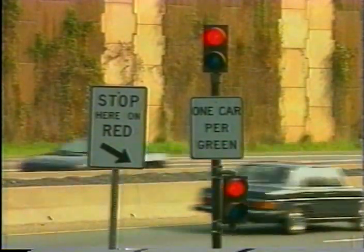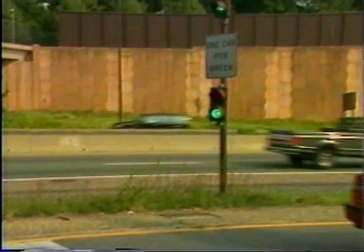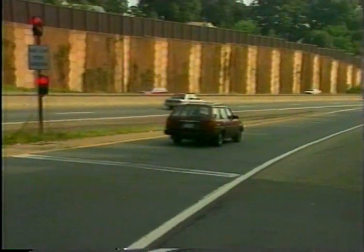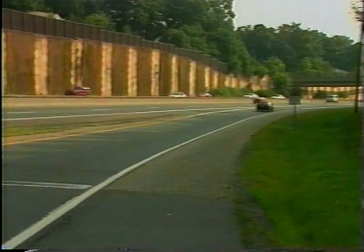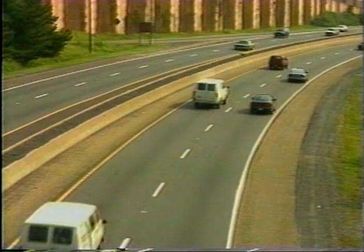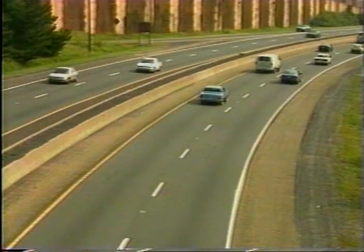Freeway ramp control signals are standard traffic control signals installed at the entrance to freeway on-ramps. They are either 2 or 3 lens signals with red and green or red, yellow, and green lenses. During peak traffic periods, the devices help control the number of vehicles entering a freeway. By only allowing one vehicle at a time to enter the freeway, they smooth the traffic flow and improve freeway capacity. There are several conditions where ramp control can be beneficial.